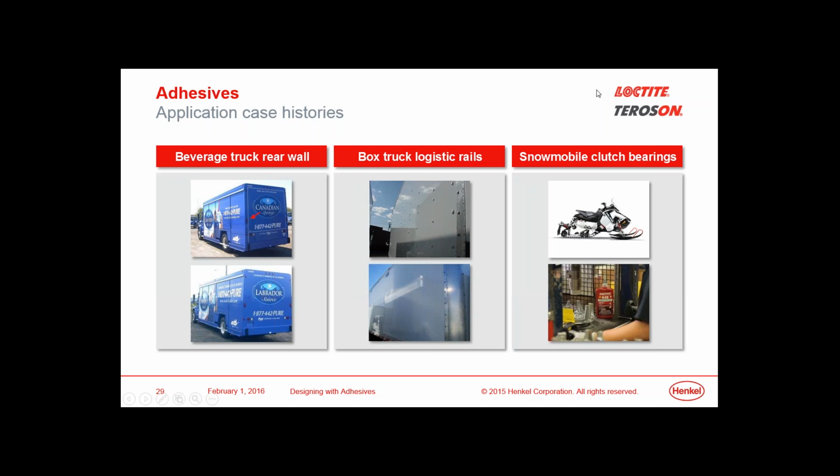They were assembling the walls to an aluminum frame, and they had to pre-drill each one of the holes in order for the rivets to be assembled in place. And then they would put, as you can see with the red arrow, a white plastic cover over the rivets on the outside. That would be put on there for aesthetic reasons, so you wouldn't see the rivet heads.